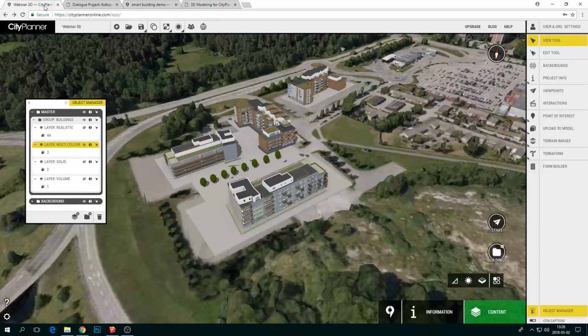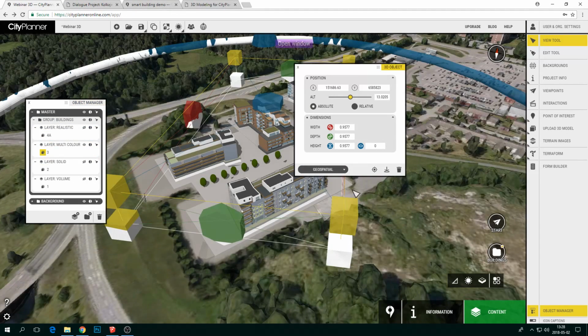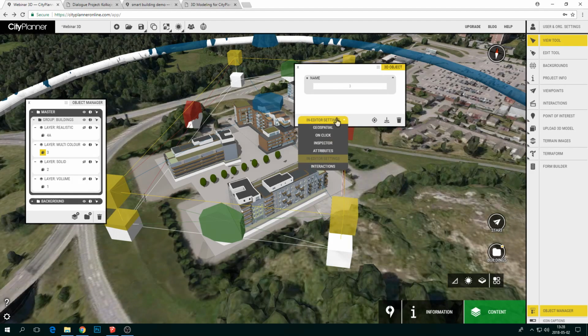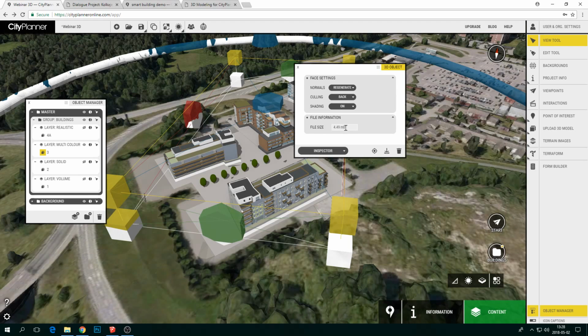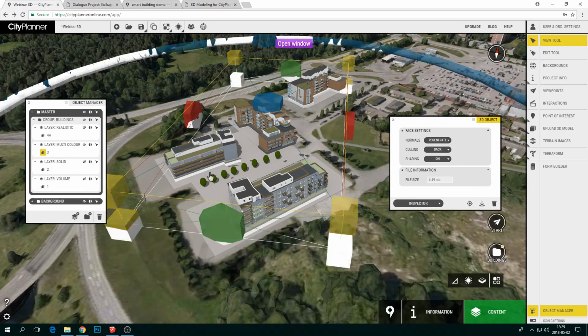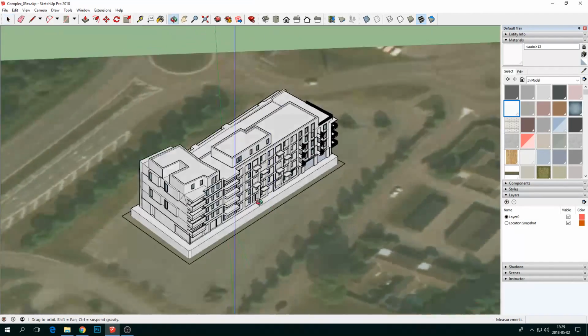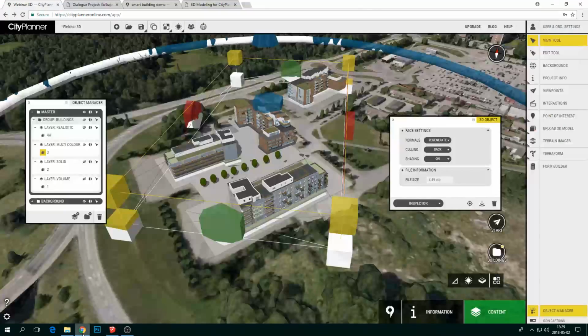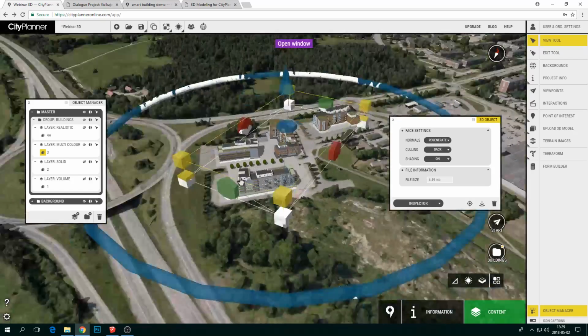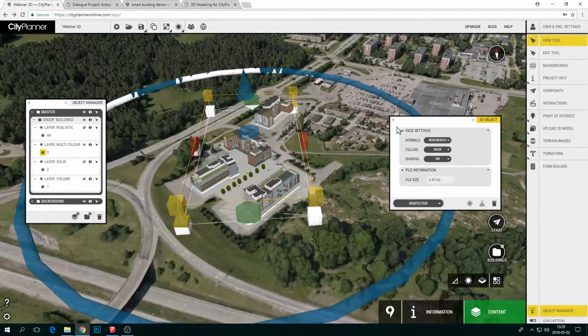And one last thing we can look at here, we can also check the model. The Inspector here shows the actual size in megabytes. So this one is 4 megabytes, and this actually contains, as we said before, 4 houses. The one we were working with here was just a single house. So it is recommended to import them one by one, actually, not doing like this to put everything in a big folder. So less than 5 megabytes for all of those buildings. That's pretty good.